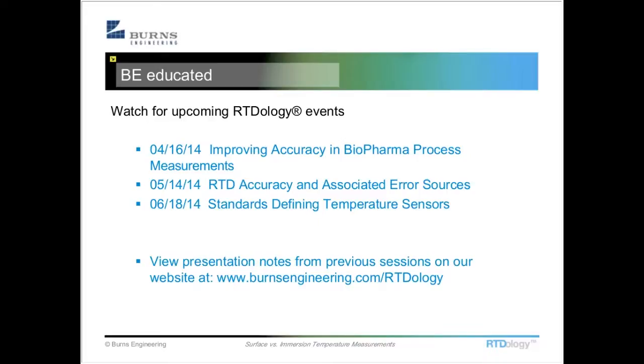Okay, then another question here. At what length of the RTD or thermocouple lead wires would you recommend using a transducer for signal stability? Might be talking about a transmitter here. Yeah, this would depend a little bit on, in the case of an RTD, if it's a 3-wire or a 4-wire system. In the case of a 3-wire, there is an error associated with 3-wire systems, and it amounts to about 0.16 degrees Fahrenheit for every 100 feet of 18-gauge lead wire.